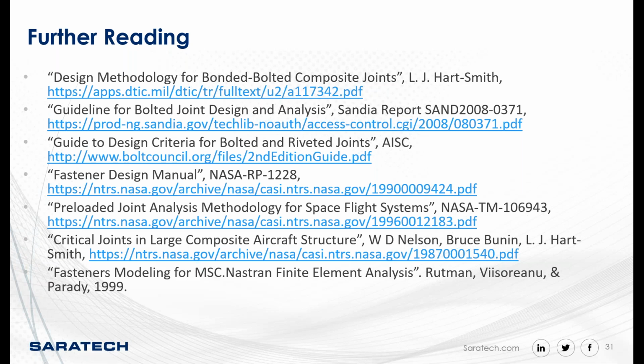inside FEMAP for defining that. One option says include the effect of thickness and offset on the contact. In other words, Nastran will calculate in physical space where the upper surface of your 2D element should be, and ensure that that contact then occurs there. If you don't turn that option on, then, assuming you've modeled it at a midplane, it's going to perceive that as being a gap, and it's going to close that gap.